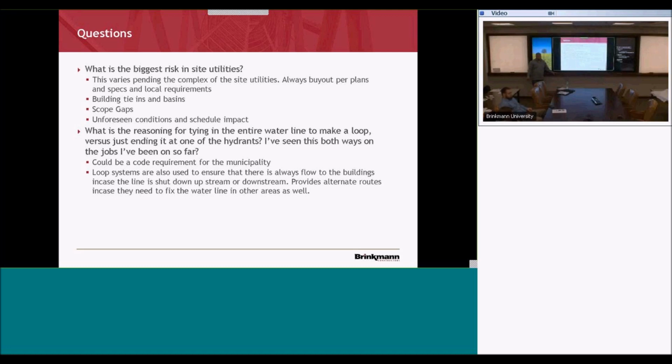Any other unit cost advisories? I got the advisories. Coordination: make sure your architectural plans do match your civil plans. If your finished floor elevations are different and your civils are higher, then that's going to cause you some issues in structure height, sidewalks, drainage, and the way that your site's balanced too. That was one that got through ours.